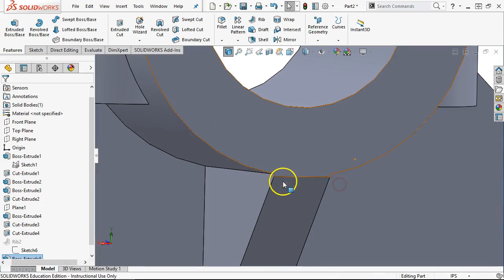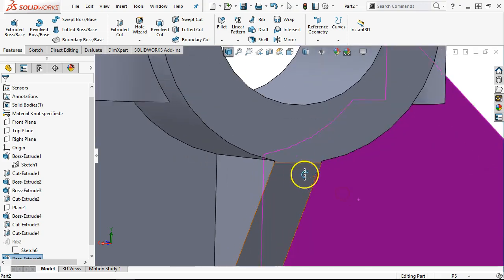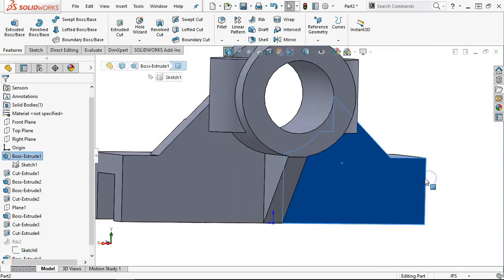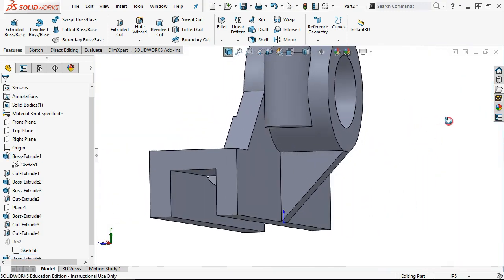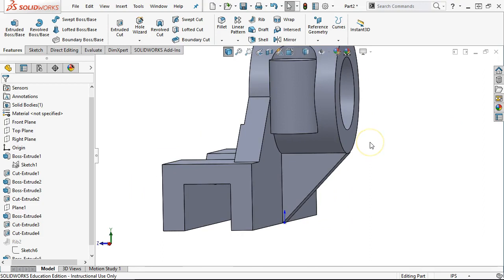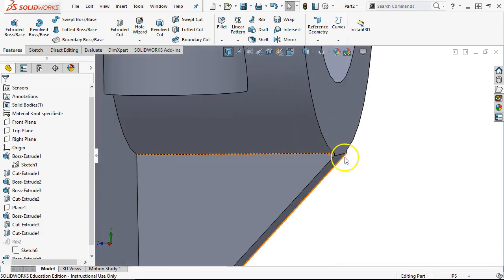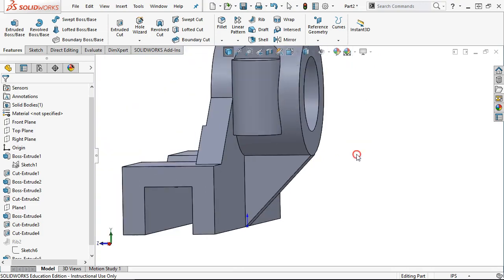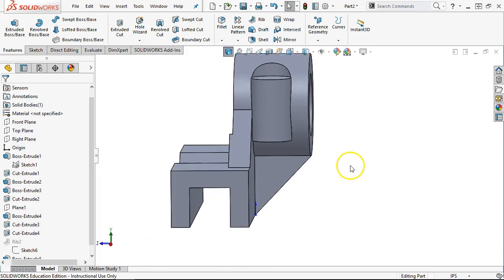And so the difference is I have this kind of square step. And if we put a generous radius in there, because we're not going to machine to a square, and it's certainly not going to be cast to that hard edge. So, either one, we could make a configuration and see what the difference in mass is of having a little fingernail versus adding in a couple of cubic millimeters of material. All right, so a couple of choices, but you have to be aware of the geometry.